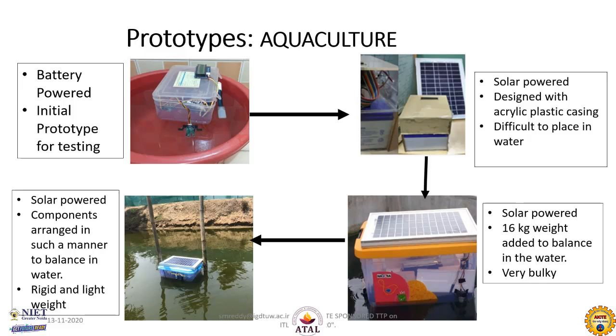The second problem we found was that under the tree there was another node. There were a lot of bird droppings, which resulted in the efficiency of the charging circuit going down. You never think of such issues unless you go there in the field and try to address them, and that was really a learning. So when you start any product design, you need to interact with the end users, see the field conditions, and then design it. Of course, there are several challenges in this product design which we have faced and tried to address one by one through various iterations.